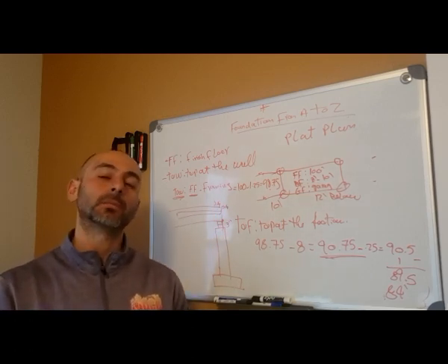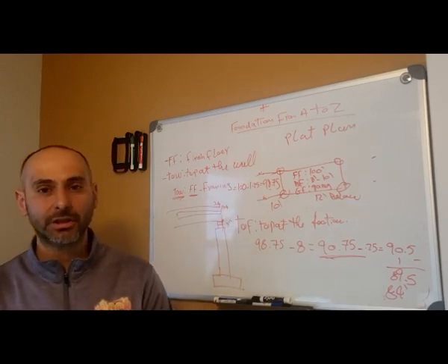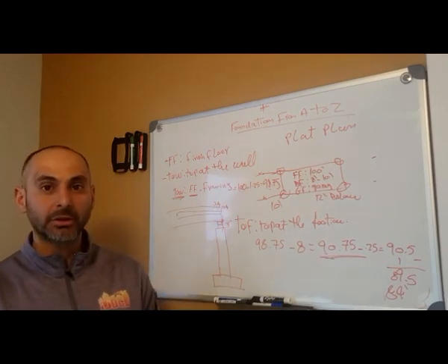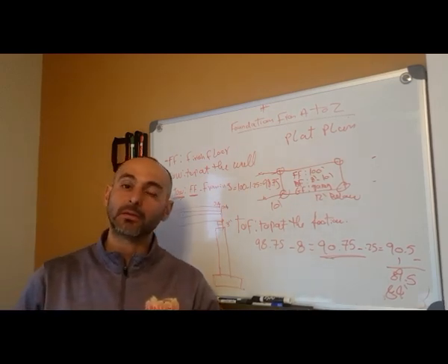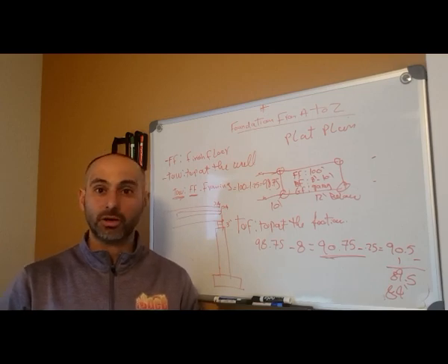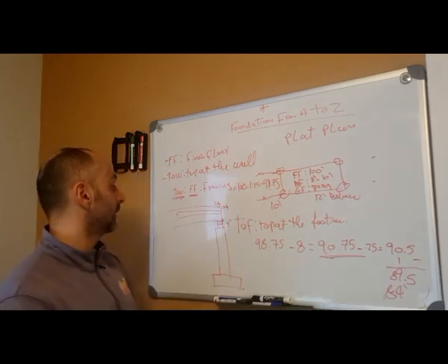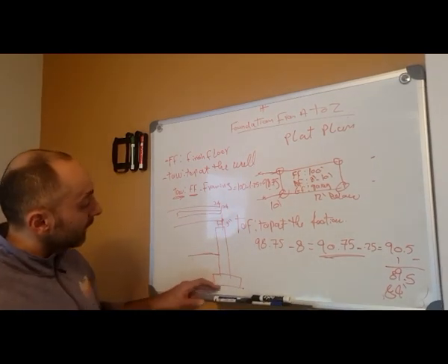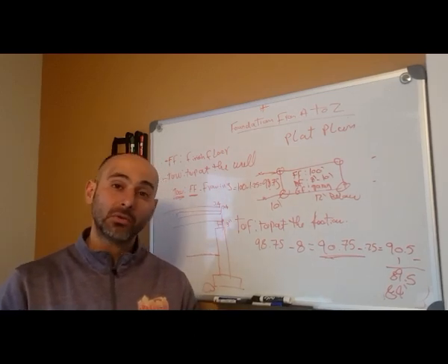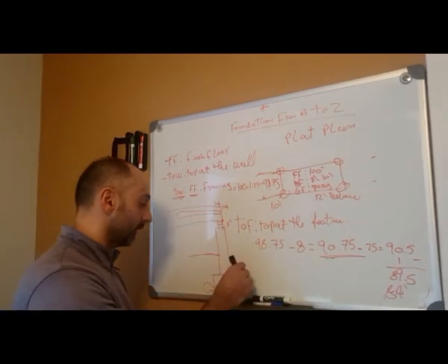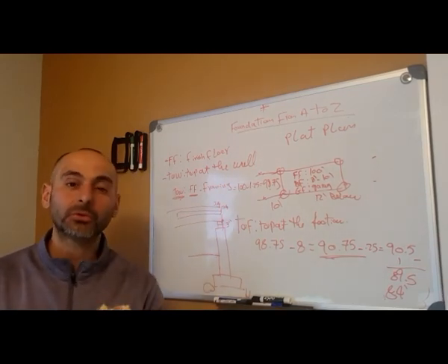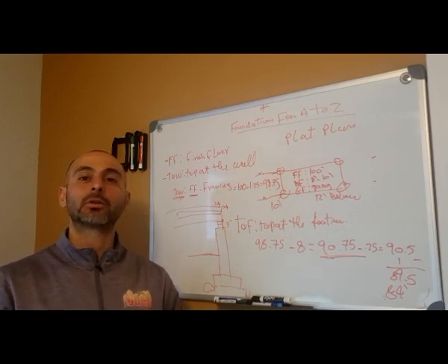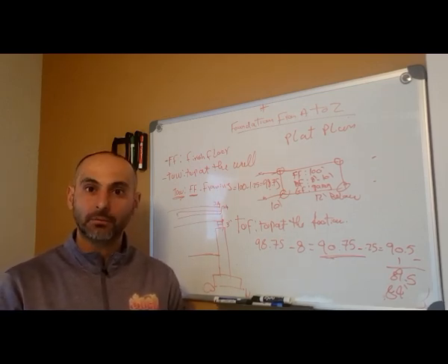Some projects will ask an engineer to come and test the soil before you even put the footing. Okay, so you compact good, you put a stone. Now look at the weather when you do excavation. Keep communication with the site contractor. If it's raining, tell him to stop. Tell him to stop 2 feet before he reaches elevation, because if he hits his elevation and it rains and the whole ground turns to mud, he has to excavate deeper to take out all the loose soil and loose mud, and put good stone and have virgin soil to put his footing on.